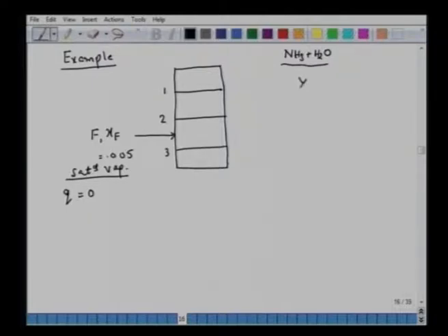Thermodynamically, we have the equation y equal to 12.6x over the concentration range of our interest. We are trying to simplify things here, so that we have only 3 trays, and the equilibrium line can be written by this equation. Feed enters between the second and third plates, and let's say the reflux is at bubble point, so it's also a saturated liquid, and we have a total condenser.